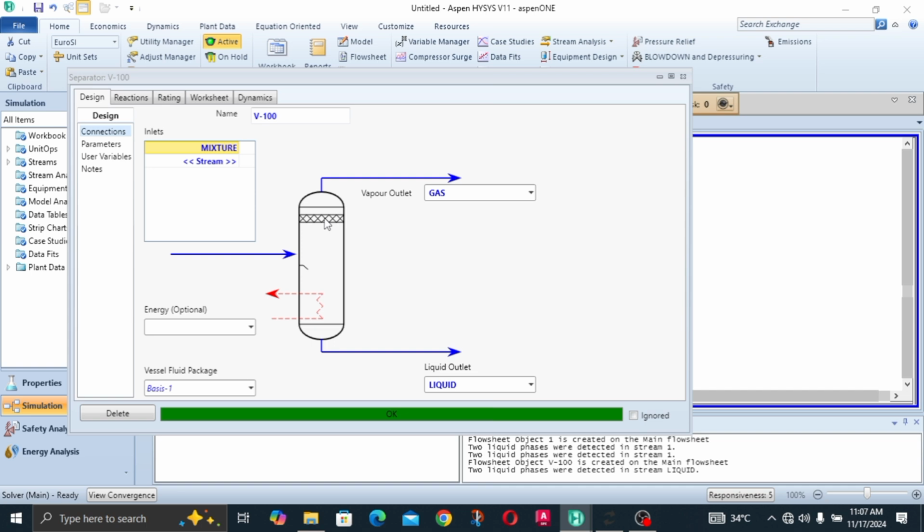So that's what it does. When the gas moves above it, the gas is able to pass through the demister, and the water molecules are being trapped in the padding. After a period of time, when it gets drenched with a lot of moisture, it starts to drip. The water trapped in the padding drips back down to the bottom, where it goes out through the liquid outlets. So that's what it basically is.